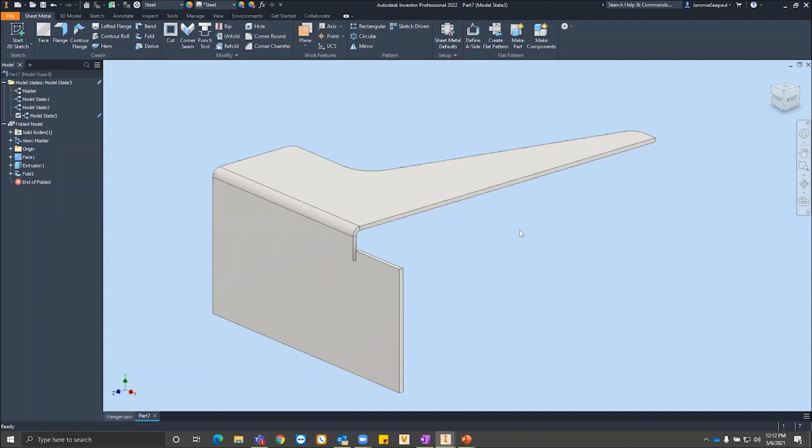Oh, go ahead. Yeah, we actually just had a question come in from the panel from Bennett, and he was wondering why use an extrude versus, say, like the sheet metal cut tool. Would there be a preference of one over the other? Honestly, I just prefer the 3D model cut. The sheet metal cuts usually, if I know exactly what the machine's going to cut or the path of cutting the sheet metal, then that kind of comes in play because that brings over a little bit extra information for you.